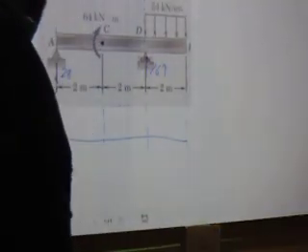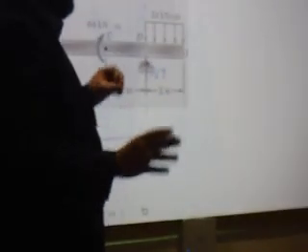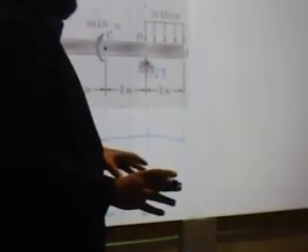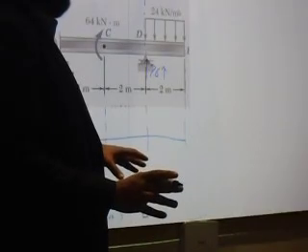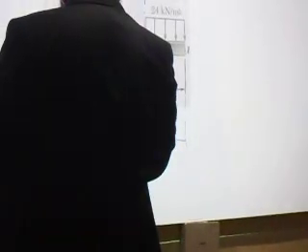So the bending moment diagram, again, tracing my points. And this point is very important. First of all, you tell me, what are the points that have 0 moment? Zero moment. A and B, the tips, the ends. Okay? The endpoints, the two endpoints. I don't have concentrated moments there, it's only the edge, nothing else.